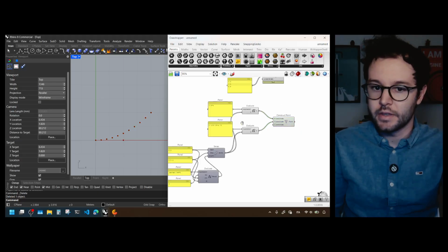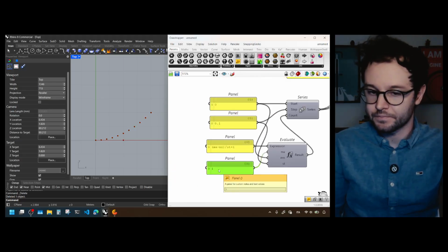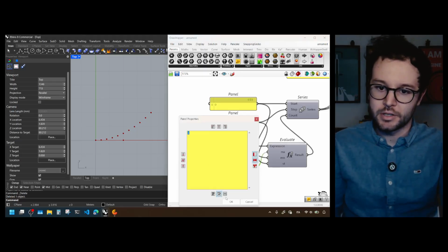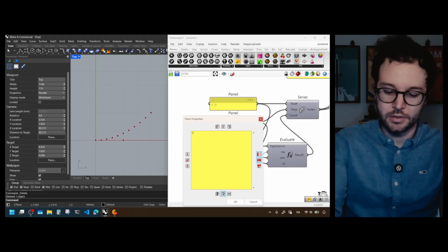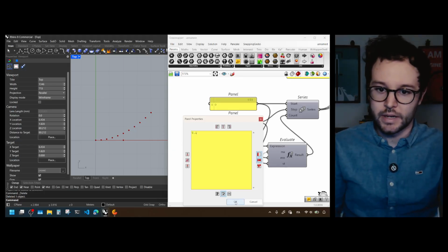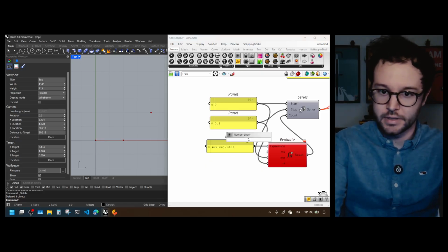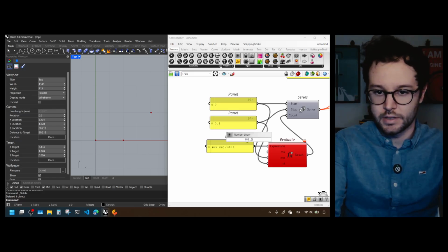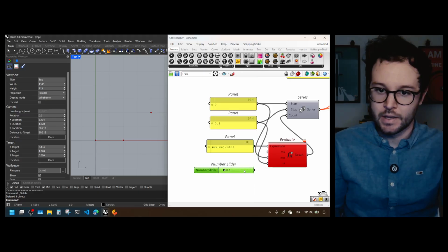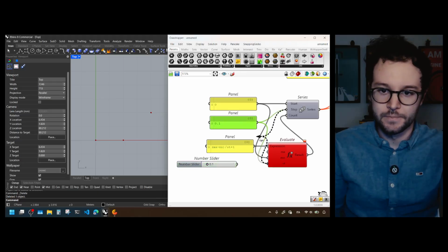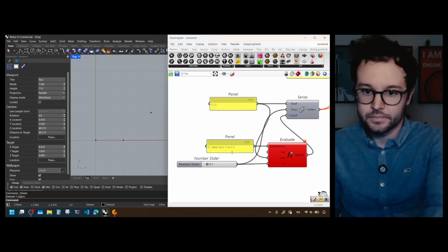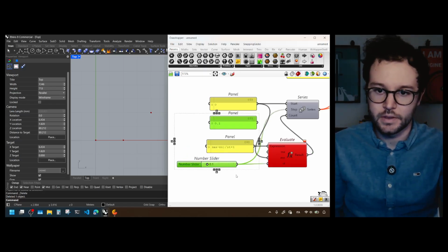Indeed, we have the same thing, but now we can use this parameter to define how much we are going through the curve. Actually, let me put a slider in instead. Let's initialize it as 0.1 to 1.0. The 0.1 is the step, and this is the maximum value.